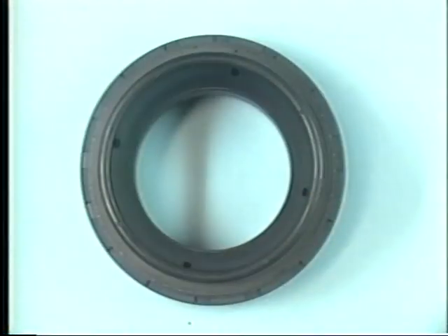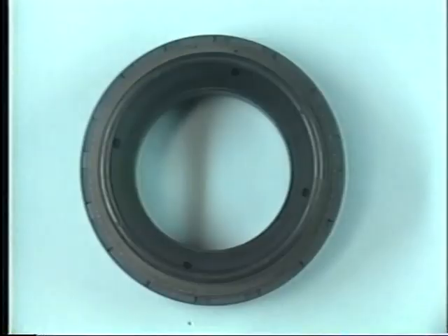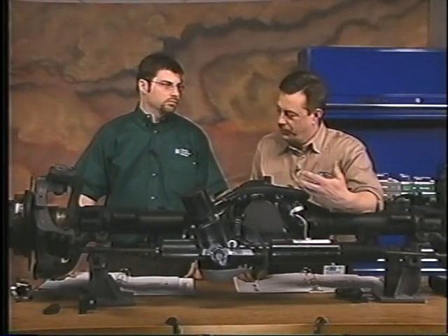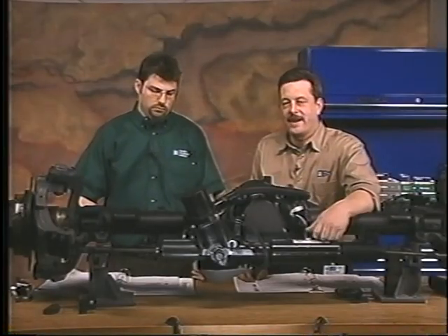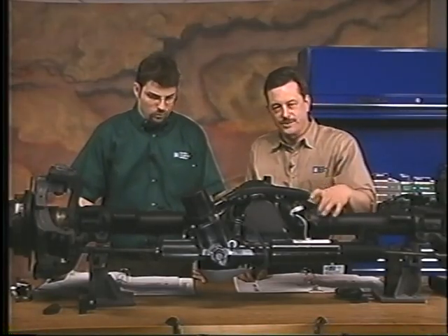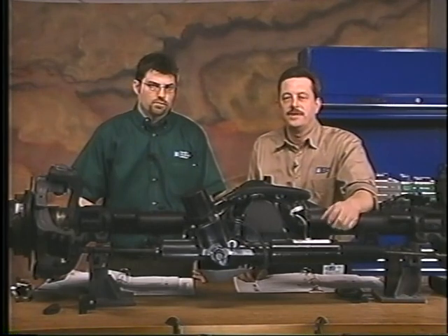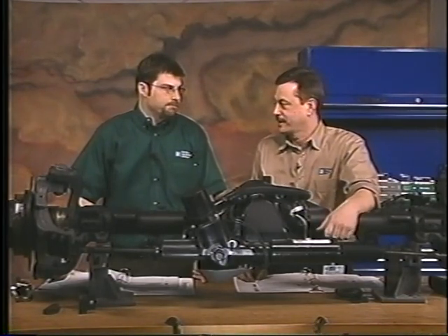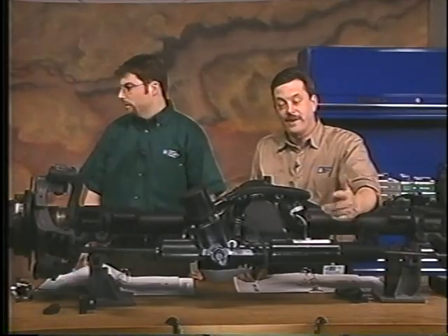Now, it does appear that this is a pretty good design. I haven't heard about any problems on this. Last time we asked, warranty was saying, nope, not a big deal, don't have any claims for those. So hopefully not something we have to go after. It is very complex, though. We're going to have to disassemble the rear axle here. Obviously, got to pull both axle shafts out. Then, once we get all that out of the way, we can go ahead and pull those seals out from the inside. To reinstall them, you need the small block V8 cam bearing installer. That's the tool we're going to use. But it sure sounds like a lot of work. Yeah, hopefully you don't have to go there.